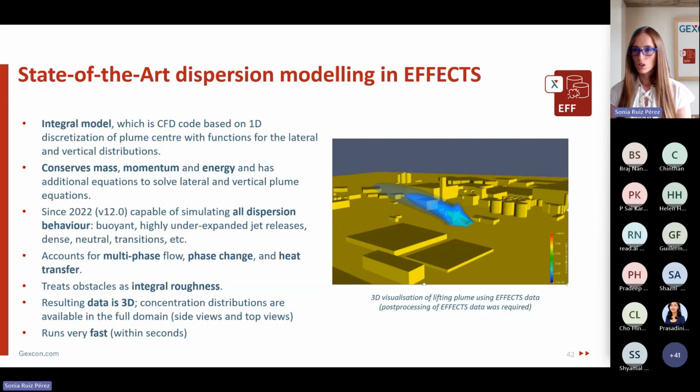So the dispersion model will also take into account how for CO2 we have suspended solid snow particles which sublimate, enhancing evaporation and a bigger flammable cloud or potentially toxic cloud. So all of this behavior is taken into account, and same as I mentioned before for ammonia, which when it's released refrigerated, it first behaves as a dense gas and then it behaves as a buoyant plume. All those transitional behaviors are taken into account in the dispersion modeling.